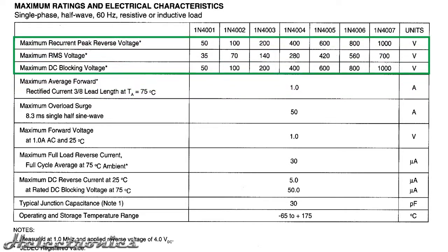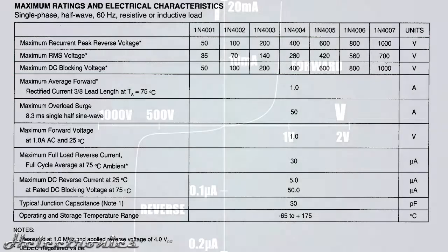It has also reverse breakdown voltage, which is a limit of reverse voltage it can block before it breaks down and starts to conduct. In the datasheet this is mentioned as maximum blocking voltage. Exceeding this value causes the diode to stop blocking the reverse voltage.